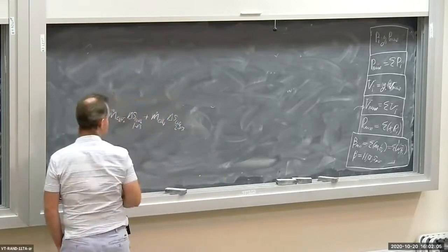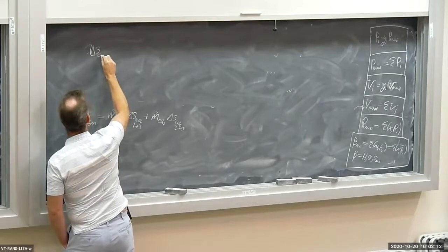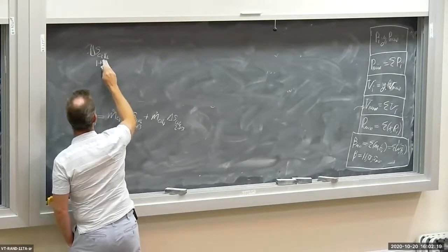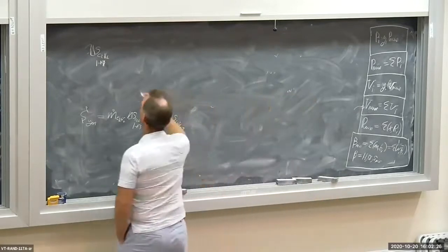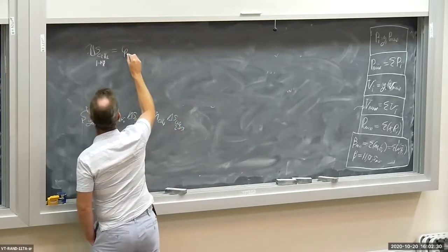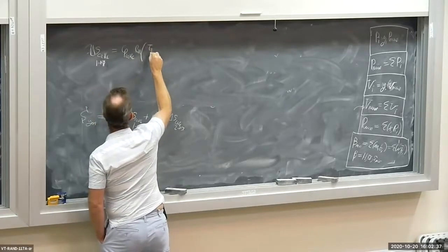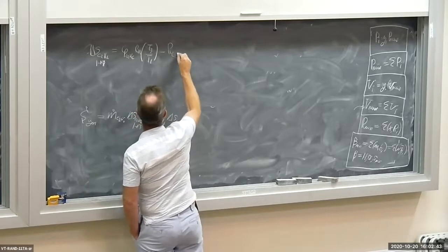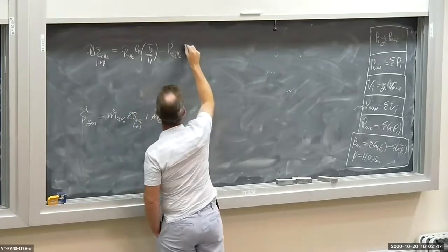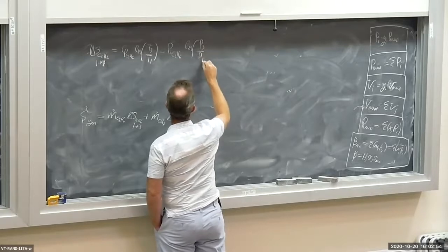Let's see here. Delta S of the ethane, C2H6, as I go from inlet port number 1 to the outlet mixture port number 3, assuming constant specific heats, is going to be equal to Cp of the C2H6 ln T3 over T1 minus R for the C2H6 times the natural log of P3 over P1.